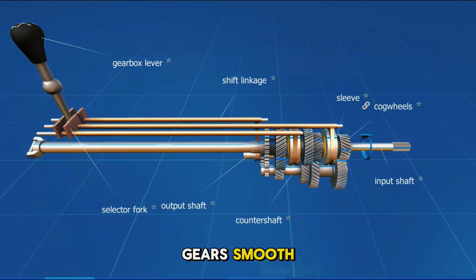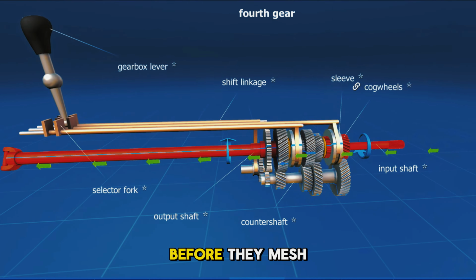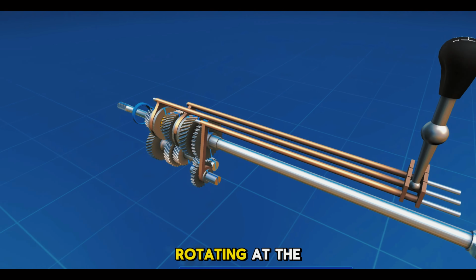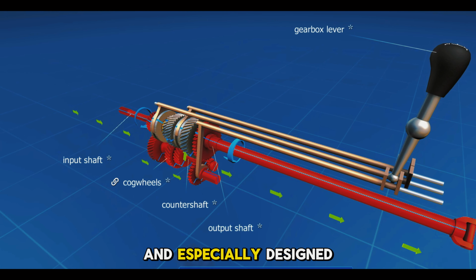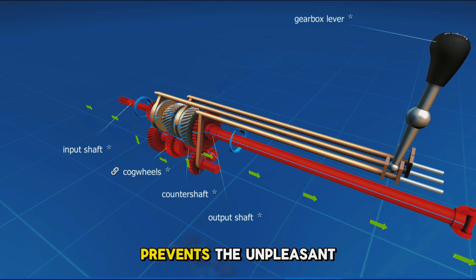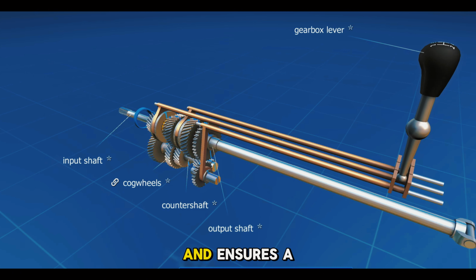To make shifting gears smooth and to avoid noise or damage, the gears must rotate at the same speed before they mesh. This is where the synchronizer comes into play. A synchronizer ring is a component that ensures the gears are rotating at the same speed before they engage. It uses friction and a specially designed surface with sloping edges to equalize the rotational speed between two gears. This synchronization process prevents the unpleasant grinding sound that occurs when gears of differing speeds attempt to mesh, and ensures a smooth, silent transition from one gear to another.